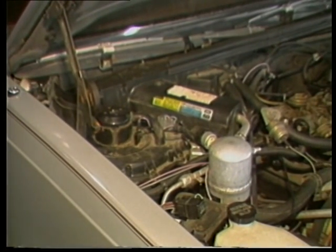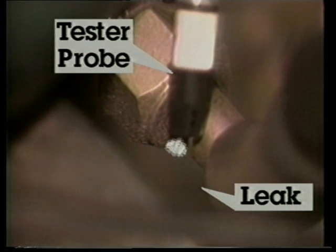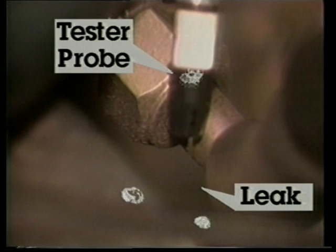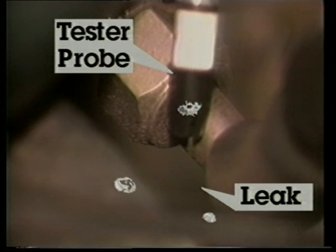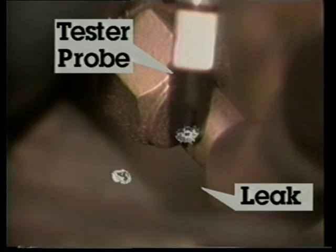During operation, the electronic leak detector pulls a sample of air into the test probe and up into the tester body. If refrigerant is present, it will trigger the tester circuitry to make the sound change in tone or frequency. It is highly recommended over the older, dangerous flame-type leak detectors.